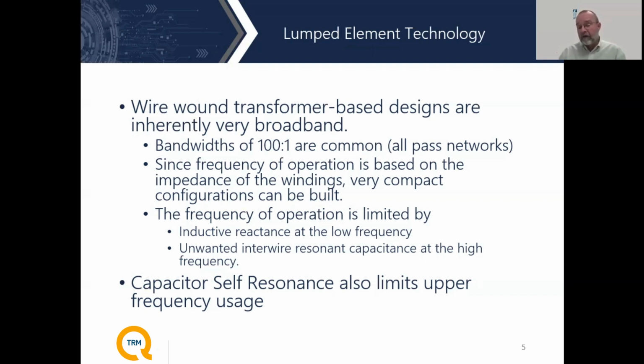Its limiting factor is that we have to watch the self-resonance and parasitic capacitance of the individual elements that we're using to make this technology. What this does is it limits the higher frequencies, where these parasitics become unmanageable. So lumped element technology tends to be a lower frequency realization of these circuits. And like I said, with low frequency operations, lumped elements are a great solution.